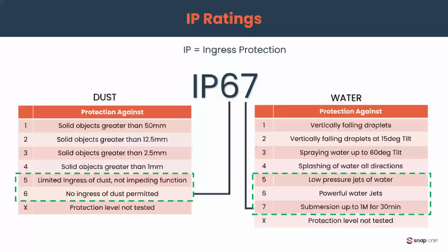One of the questions was on wiring and whether or not it's okay to use normal speaker wire and a Schedule 40 pipe. I would say, while yes, it's probably doable, it's always recommended to use burial wire. You're never going to fully prevent against moisture in the ground unless the pipes are fully sealed all the way up until out of the ground. And so it's always recommended to use burial wire. Schedule 40 is super helpful for future proofing. If you want to run additional wires, you can snake the wire through the Schedule 40.